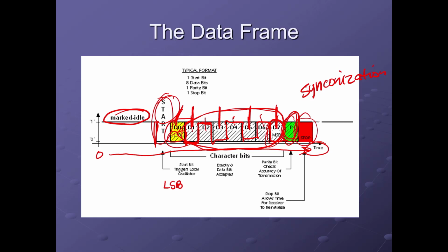And so when it comes to connections that we're going to find in the lab, you're going to find that just about every connection you're going to configure is going to be something called 8N1. So what the 8 part means is it's an 8 data bit character. What the N means is that there's no parity. So that is to say, this bit that's shown in this frame is not there at all. There's no parity. And then lastly, there's one stop bit.